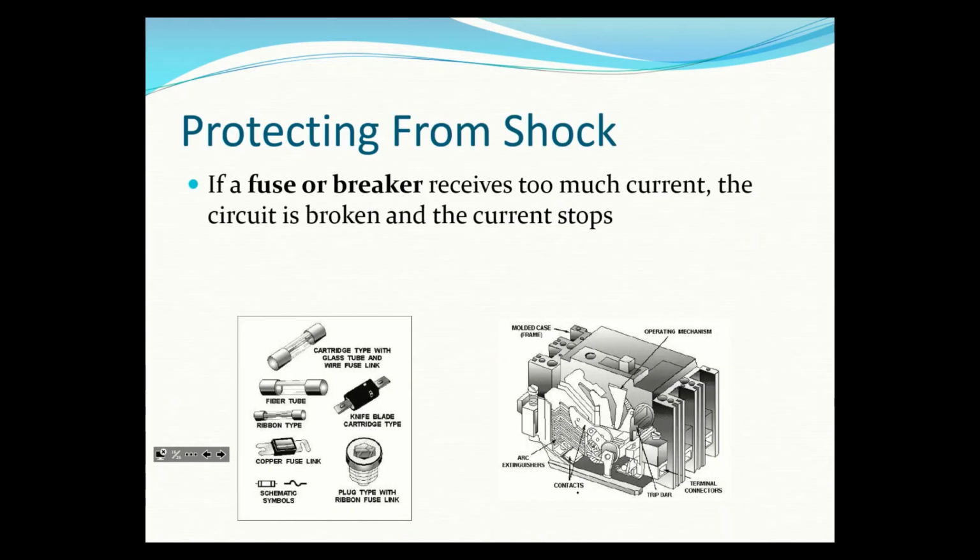So a fuse or a breaker, if it receives too much current, the circuit is broken and it stops. So this is what fuses look like. Fuses all work on the same idea. They all have a wire in here, and when current goes through a wire, it heats up. So these are special types of wires that when they heat up, they burn up. So if too much current passes through here, this will burn up and it'll stop the current from flowing across there, so you don't start a fire. So all these are the same sort of way.